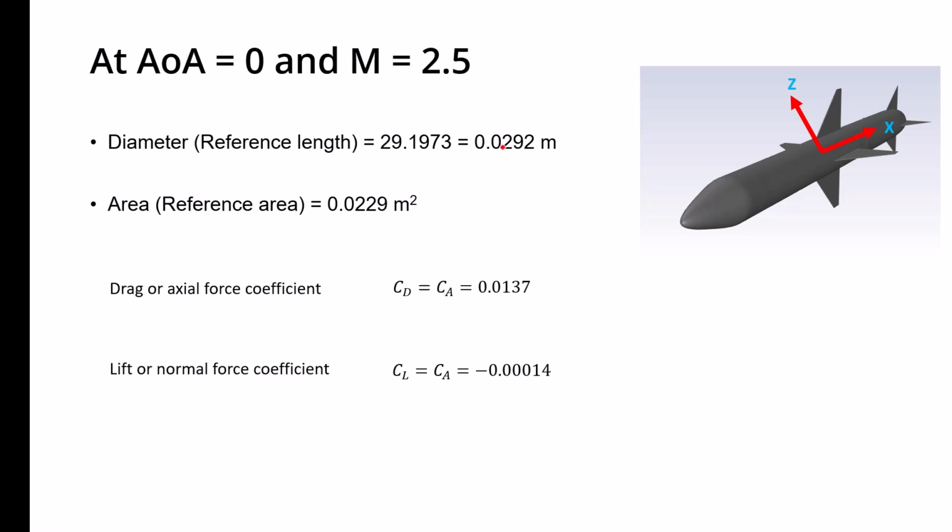One more important thing is that in aircraft we actually go with the mean aerodynamic chord and the projected area, but in the case of a missile, the reference length is the diameter. Okay, this circle, because this is the reference area and length. Its diameter is D. So its reference length is the diameter and the reference area, A reference, is pi by 4 D square.